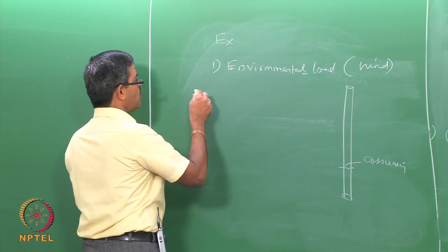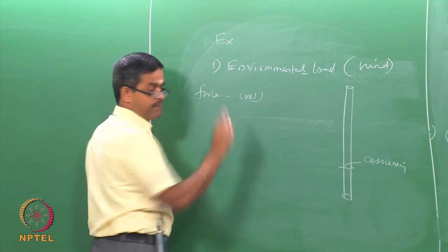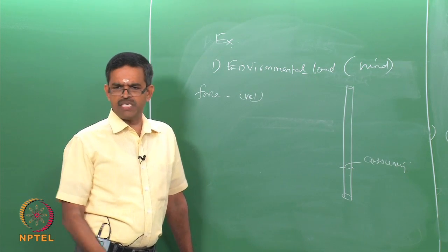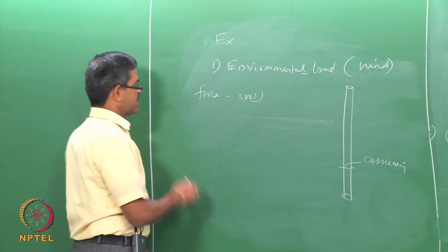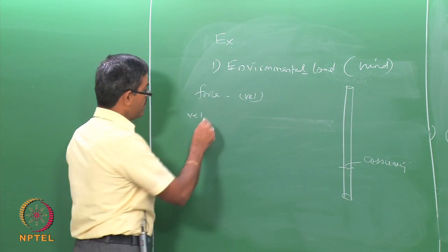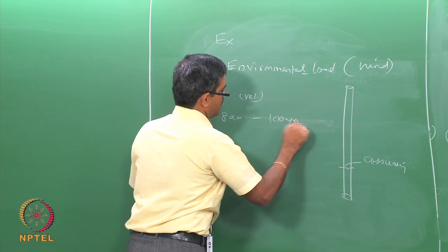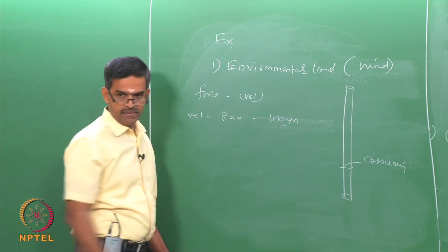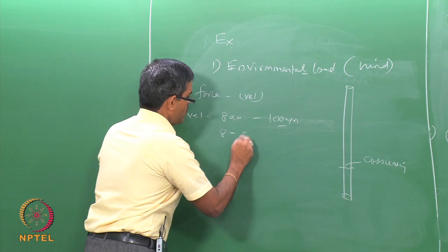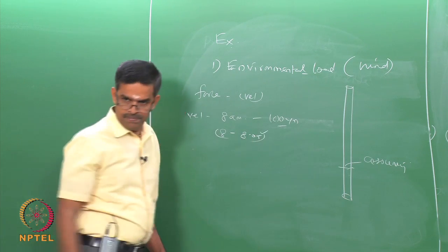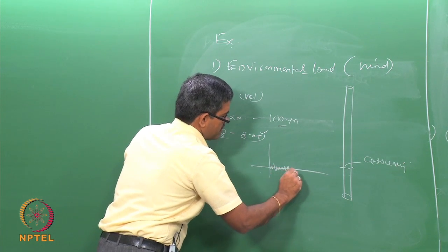Now, you are trying to find out the force which is dependent on velocity, and velocity depends on various parameters like surface terrain, height, time, etc. Let us say I take the velocity of wind every day at 8 a.m. for 100 years. I measure the wind velocity for 5 minutes, let us say 8 to 8:05, and I get a history. It is not of course going to be constant; I get a history, I get a mean.